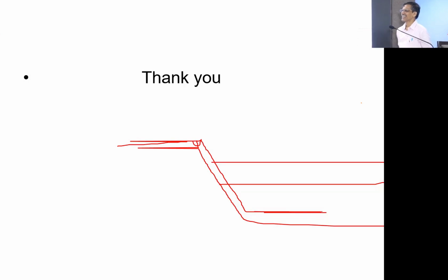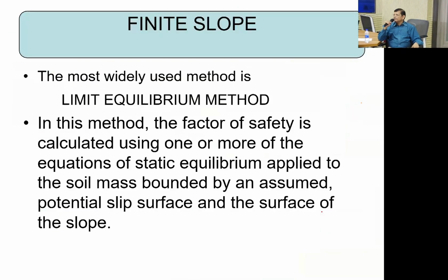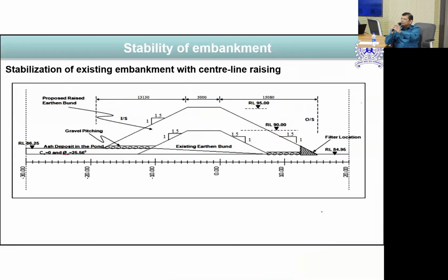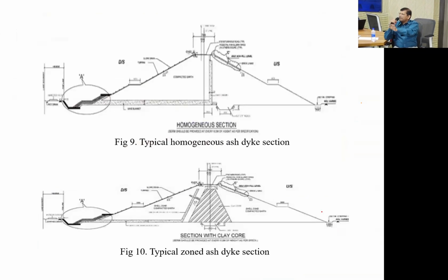Instead of a core, we are thinking of a liner. They are putting those. But the problem is, again, I can tell you, there will be a gap between the liner and the slope, along the slope. Definitely, no doubt in it. At some locations it happens. And if there is a small hole in the liner, which is possible because we are keeping it open, anything can open it. When you keep it open, anything can happen. So, if there is a small hole, your whole concept of the liner is gone now.